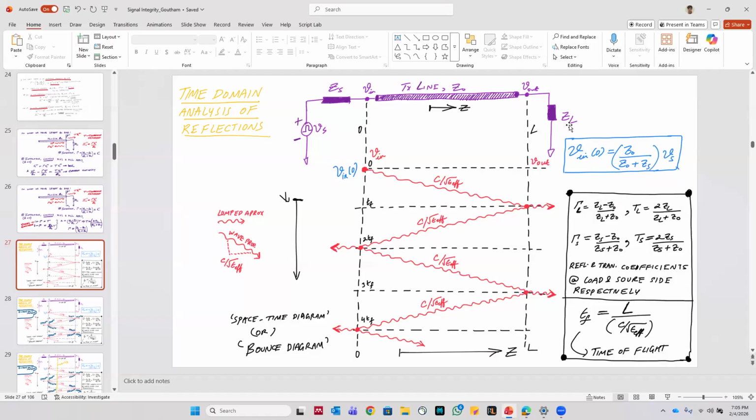So now what's going to happen is every time the signal goes to one of these endpoints, it's going to get reflected and going to get transmitted, right? Because there's going to be a reflection coefficient at each endpoint, right? So imagine now I'm sending a wave. So the wave, let's see if I can potentially draw this. Okay. I'm going to represent the wave by a box, okay? Okay. So imagine this is the wave, okay? So initially when I switch on the circuit, the wave is going to propagate like this.